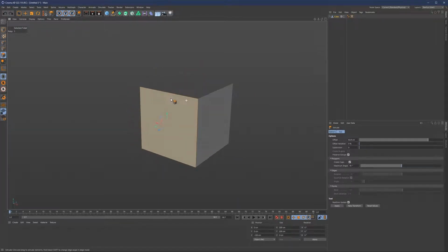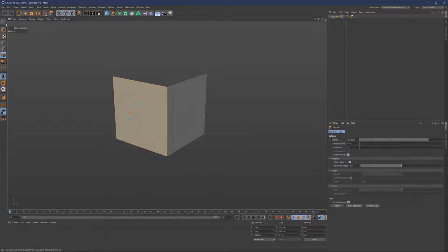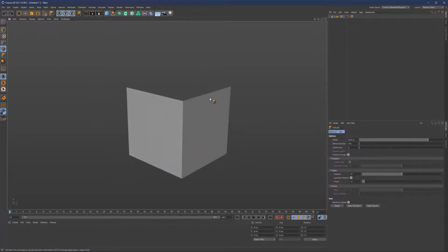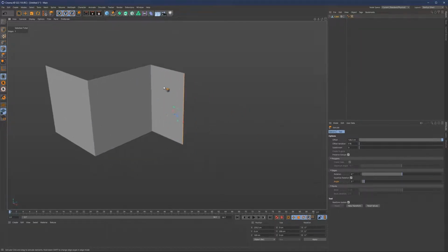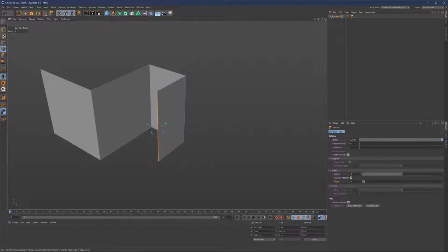And now we are in, let's say, this mode. Let's go to edges. So what I'm going to do is now cover edges a bit. You notice that the moment you switch between these three modes, this will also change. Now in edge mode, the edges become active and polygons become grayed out. The same thing applies here. You can simply extrude the edge the same way you extruded the polygons.